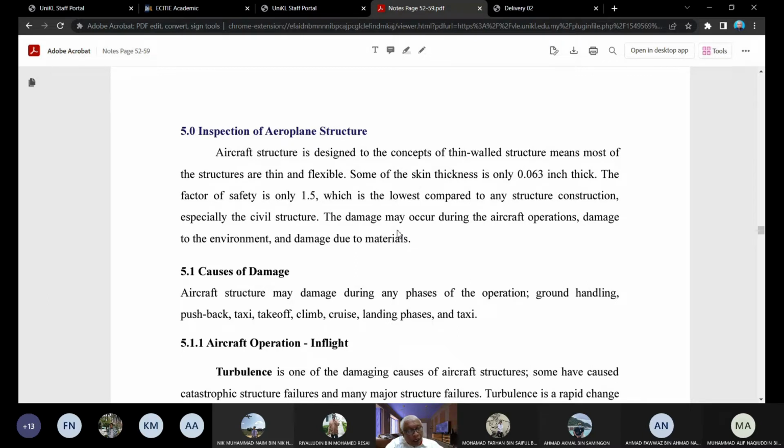However, if your airline has the design approval to do repair, you have approval by a Part 21 Subpart J organization, DOA, then you are able to do minor repair, but you still need to go back to the OEM for major repair. For the Part 21 Subpart J organization, DOA, you are allowed to approve minor repair, and then the 145 is allowed to embody the repair for minor. But for the large repair, you still need to go back to the authority.